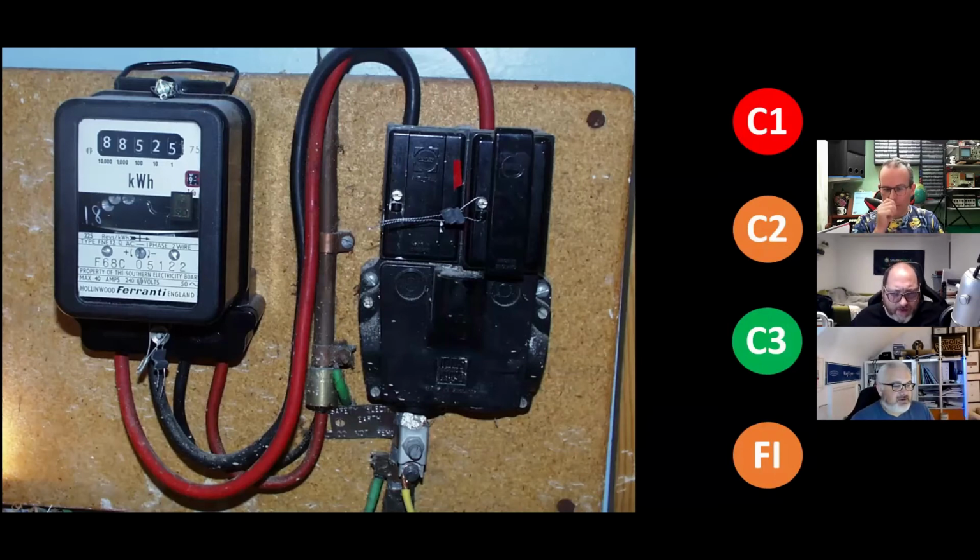So we've got what looks like a TNS supply with a couple of bits of green and yellow. Evidently an electrician has installed that because... Am I right in that the green has just gone behind the board and come back through the board? Yes, someone's been clever, tried to be smart. Why they did it, I don't know. It's only like 2 inches below. It goes in that hole and then comes out underneath and goes into the clamp. But here's the point: now it's disappeared from inspection view. Do you now have to test it for continuity?